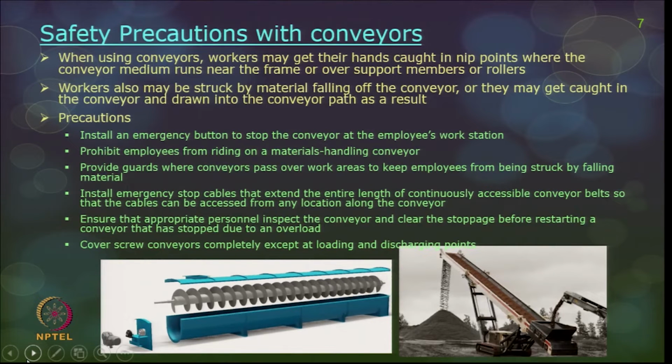Ensure appropriate personnel inspect the conveyor and clear the stoppage before restarting a conveyor that has previously stopped due to an overload. And this is primarily called a screw conveyor. This screw conveyor has to be completely covered. Screw conveyors are used for handling cement on construction sites, and especially at the loading, unloading or discharge points, the screw conveyor has to be completely covered to prevent all the hazards.